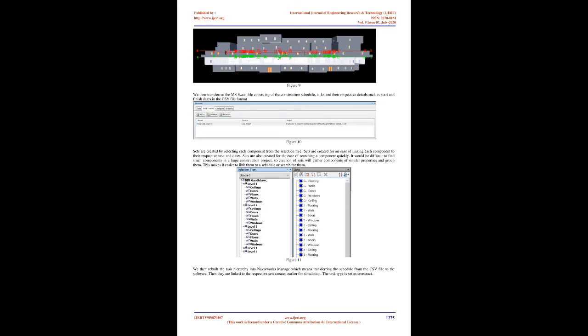On completion of the floor plans of each floor, we align the sectional view and elevation view of the building by entering the correct dimensions of wall height for each floor. The 3D model then comes into picture as we complete the final dimension of height of each floor and align each floor correctly. Now we added windows and doors to each room at their respective position. Once the windows and doors were fixed, the stairs were aligned and designed. The stairs had to be aligned for all floors from ground floor to fourth floor uniformly. Stairs need to be designed separately with the correct number of stairs, width, and inclination and then later fixed into place within the 3D model.